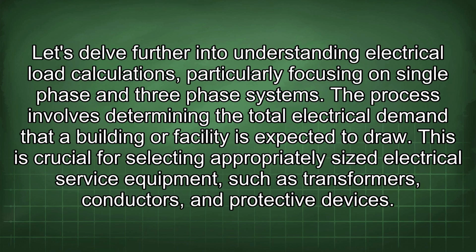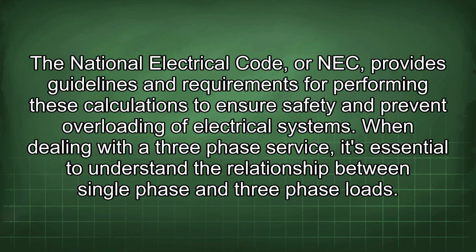Let's delve further into understanding electrical load calculations, particularly focusing on single-phase and three-phase systems. The process involves determining the total electrical demand that a building or facility is expected to draw. This is crucial for selecting appropriately sized electrical service equipment, such as transformers, conductors, and protective devices. The National Electrical Code, or NEC, provides guidelines and requirements for performing these calculations to ensure safety and prevent overloading